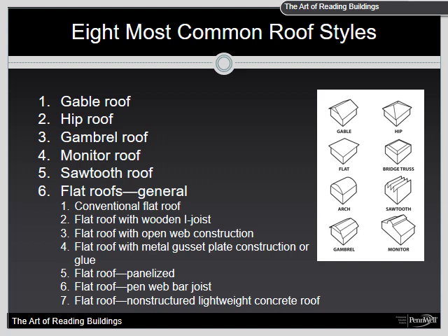Numerous supporting posts are required with a sawtooth design, which can increase the strength of this roof as compared to a similar sized flat roof. The sawtooth is very stout and can usually support the weight of ventilation operations. Removing numerous windows can achieve the desired result. Our only real hazard here, if this is built today, is lightweight construction, which uses the OSB sheeting or the smaller plywood, which has little fire resistant characteristics.